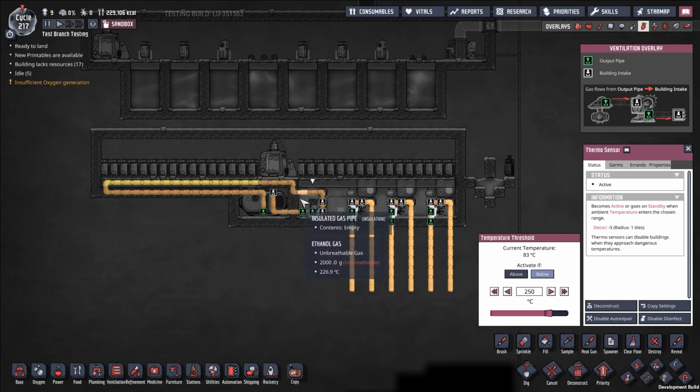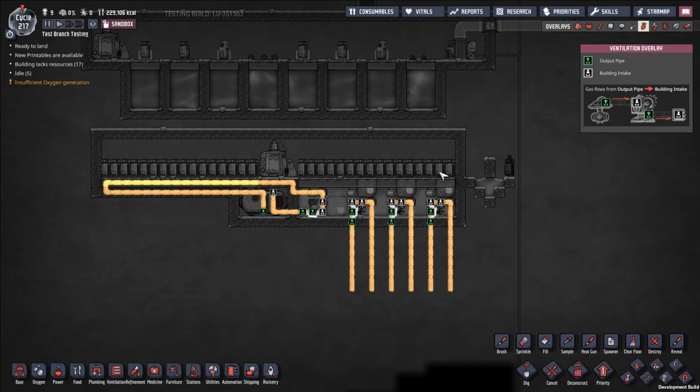So for example, if the condition that isn't met is that the coolant is too cold, well, great. The coolant will just continue on its way and then heat exchange with this system over here, hopefully become warmer in the process, come back, and then it will be warm enough for the system to turn on. If the condition is that the room itself is too hot, great. Just have the coolant kind of be in standby while more heat transfer occurs through this window tile, right? So this prevents the system from breaking.